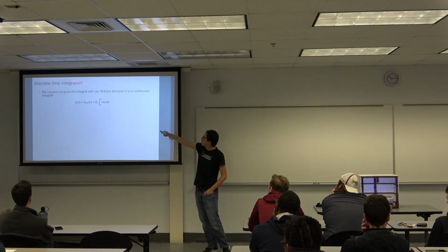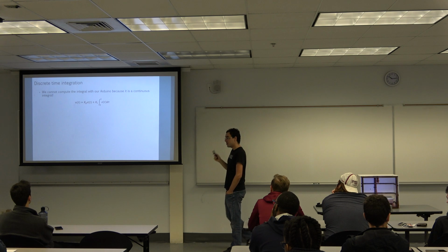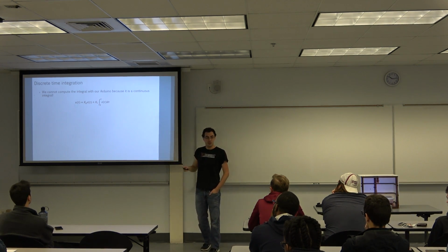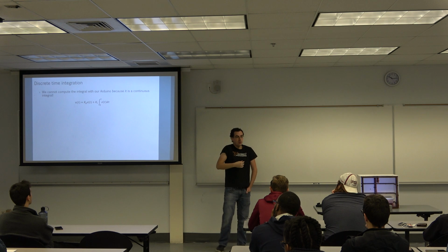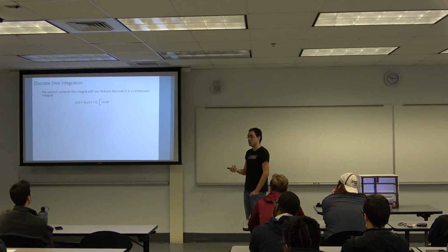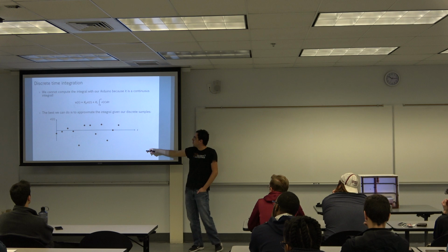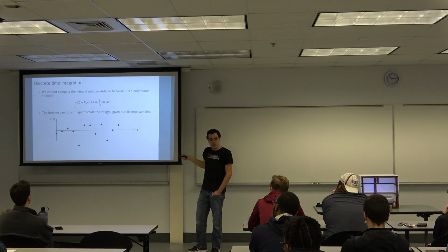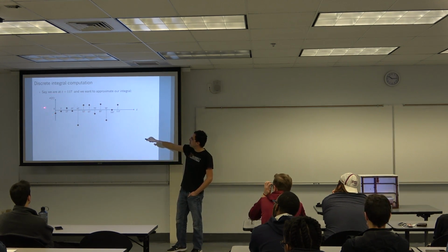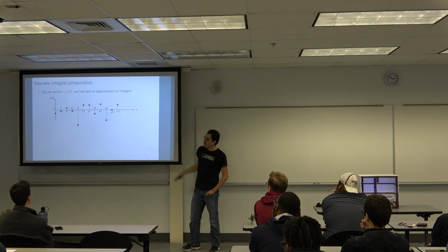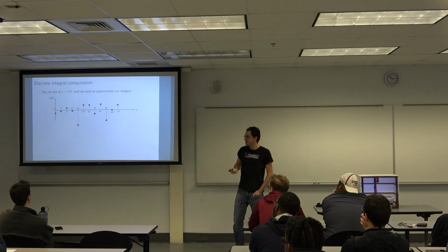Okay, so now we have to realize that we can't really compute this integral in the digital controller, because the integral is a continuous piece. We are missing stuff in between that we have to approximate. So we can only hope to approximate the integral given our samples. Remembering the chart, I'm calling E of t instead of F of t, I can only approximate this integral. So let's do a little bit of an exercise. This is a more complete version. I have here from 0 to 11T, and let's say we're at t equals 11T and we want to approximate the integral. How would you do that?